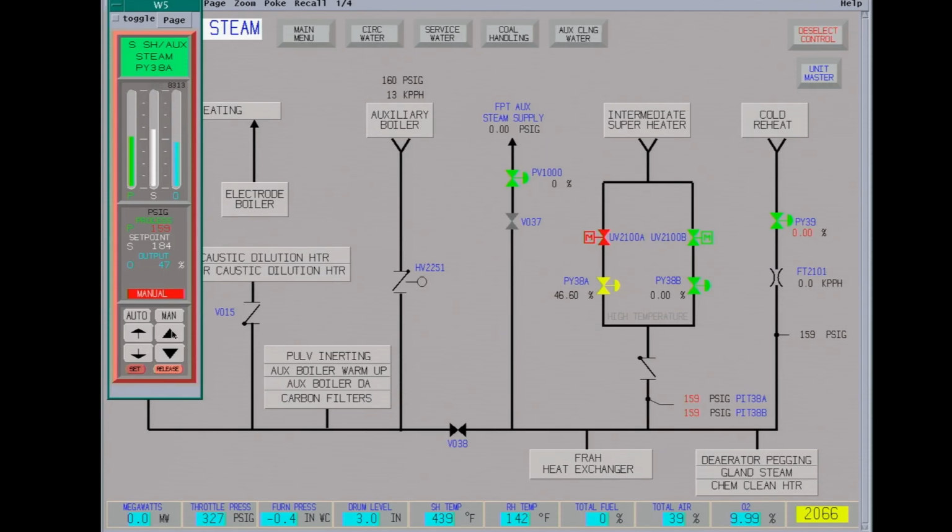You're down to about 13k pph. How's your boiler doing? It's going pretty good, I think. We're on schedule. Okay, as soon as you come offline and take over, you'll need to do the low water level test on it and then add the chemicals for shutdown. Alright, sounds good.